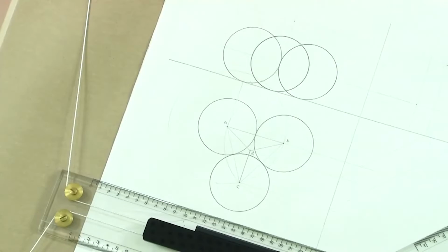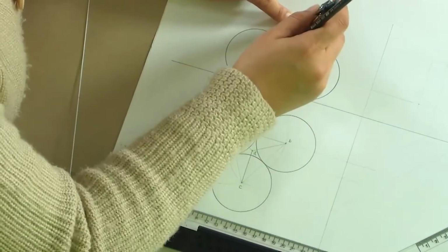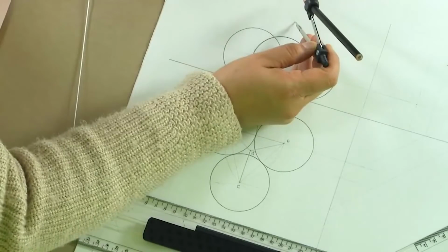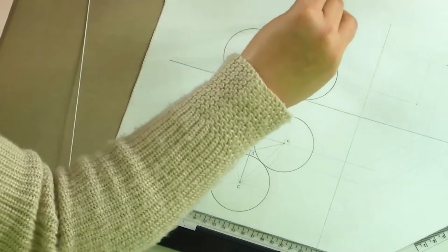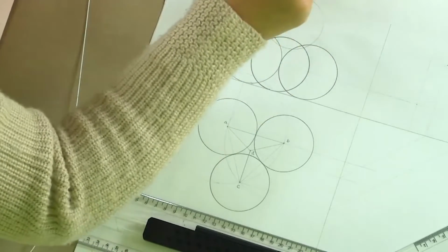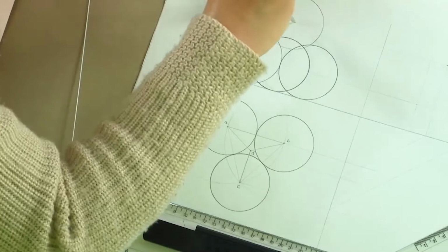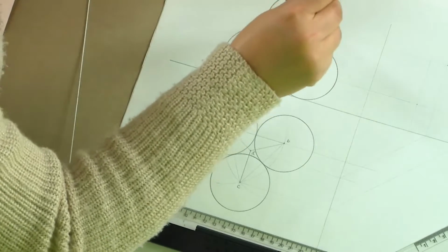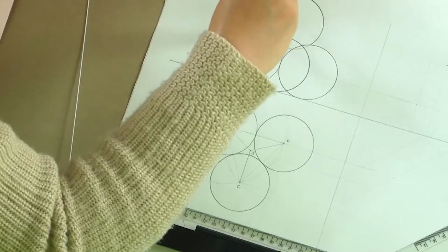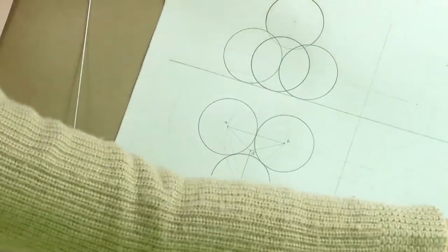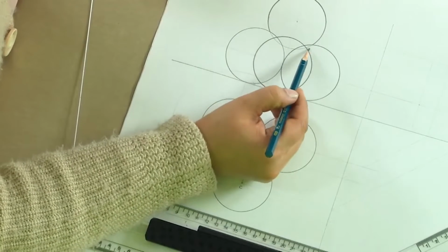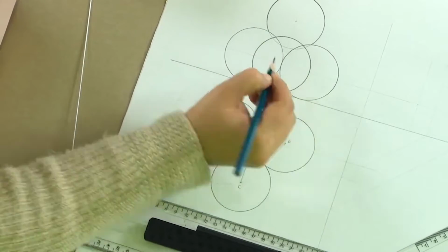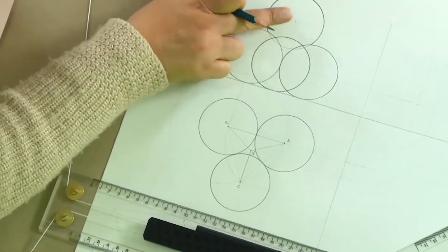And now, if I have to draw this sphere, since I know the circle here, the center here, I will take the same radius and draw this another sphere. However, a part of the sphere is going to be hidden between the other three spheres. So, we will only see this darkened portion outside, and this portion which has actually gone behind is the hidden portion. Here you might be getting confused because we did not make these lines as hidden, but I just wanted to explain to you how this point will be arrived.